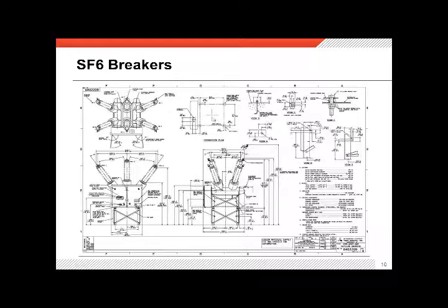Now, moving across the drawing, you're going to get some information up in this corner about how to design your foundation. And my recommendation on this is to put a slab of concrete down and then epoxy anchor in the anchor bolts. It's really difficult when they're spaced out that far to get all of your anchor bolts in correctly. And if you try to, I guarantee you're going to have a few of them where they don't end up in the right place. They got to cut them off, and you're going to have to epoxy them in anyway. So you may as well not fight it and just go that way.